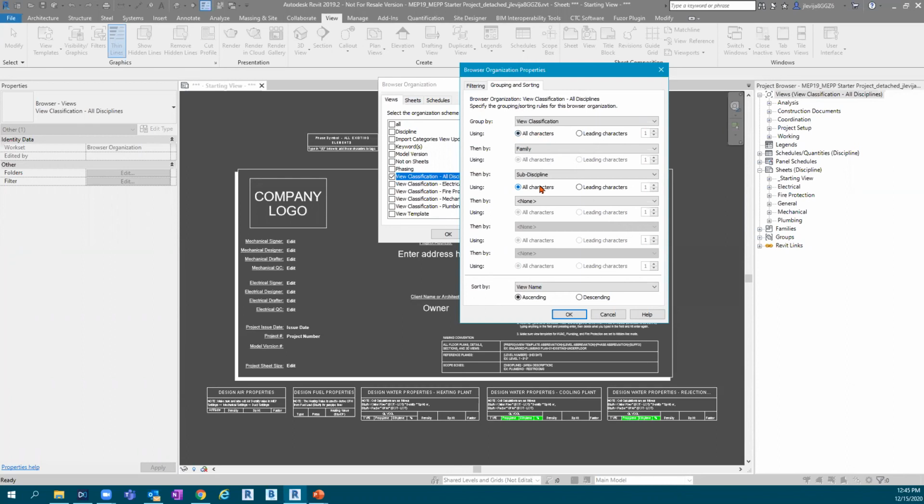So the moment we apply that view template, which is basically the snap of a finger, we're able to have that specific view show up accurately the way we have the template set up, rather than having to go in and adjust and so on and so forth. So those are some of the options that we have out here.